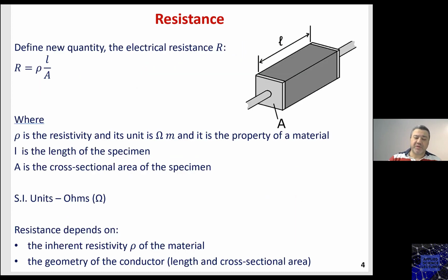So what is the relationship between the resistance and the resistivity? The resistance is the resistivity times the length divided by the cross section. Remember, we said that the resistivity is the normalized resistance. So, what does normalized mean? It is for a cube that has a height of 1 meter, a length of 1 meter, and a width of 1 meter. So, it is normalized. In order to get the accurate resistance, I need to know the dimensions of the resistor that I am measuring the resistance for, which means I need to know the cross section and I need to know the length.